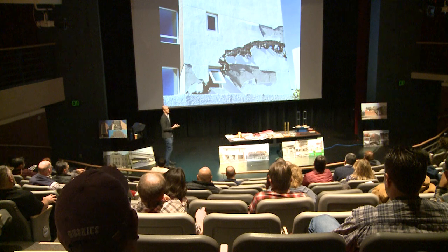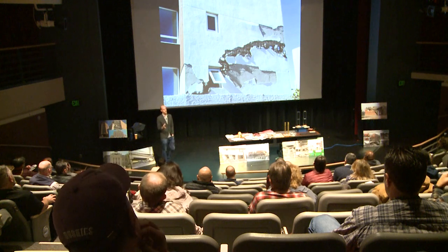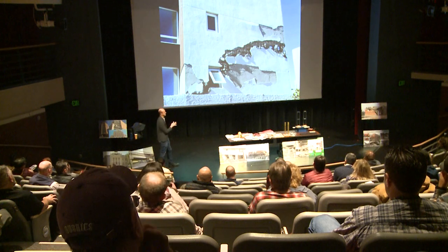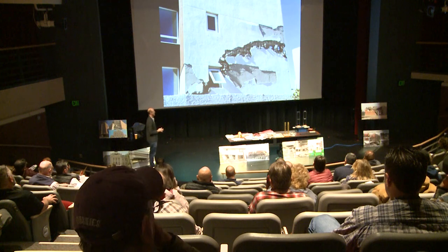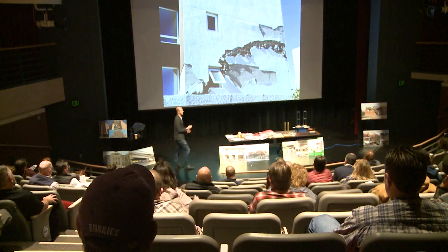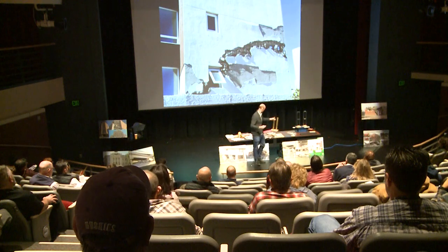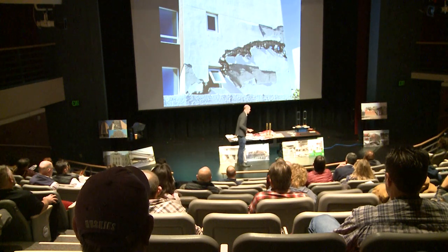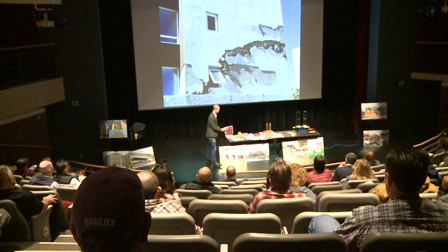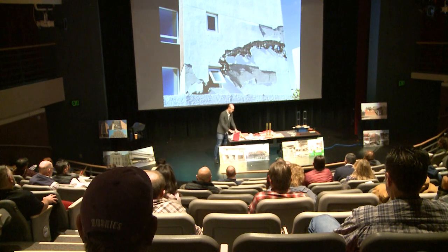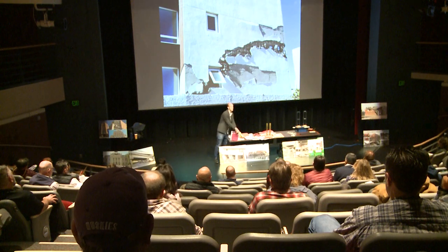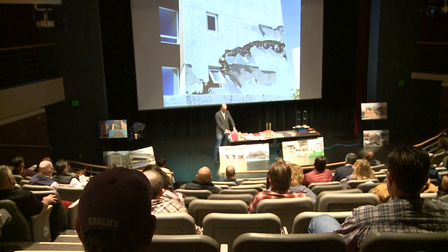The thing to keep in mind with reinforced concrete shear walls, and this particular context in Chile, is at the end of our walls, we put reinforcement as if there is a column because of those arrows that Rami showed earlier. You know, when it's rocking back and forth, it's a lot of compression on the end of the wall and tension the opposite, and vice versa.